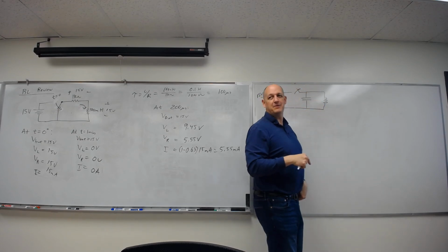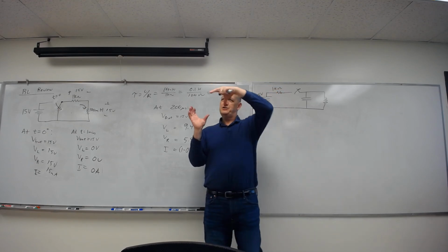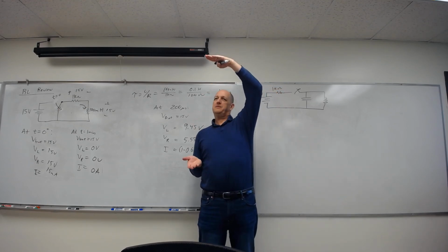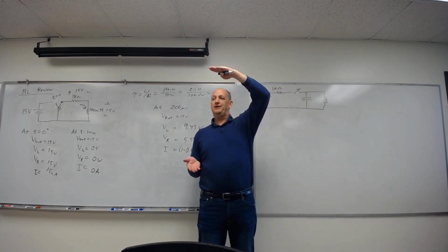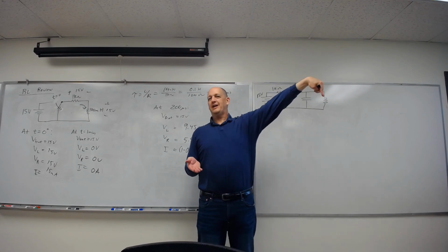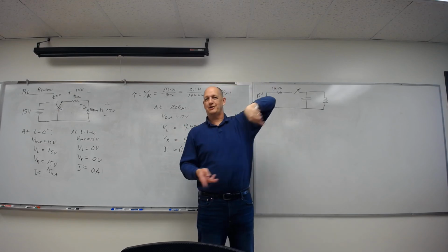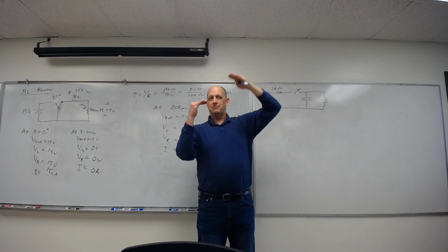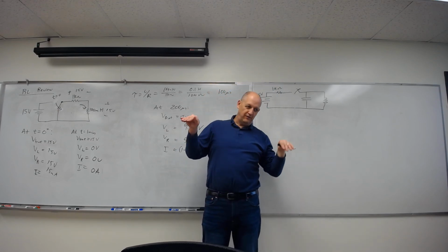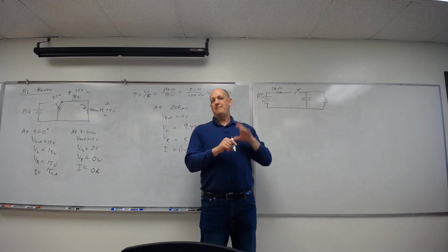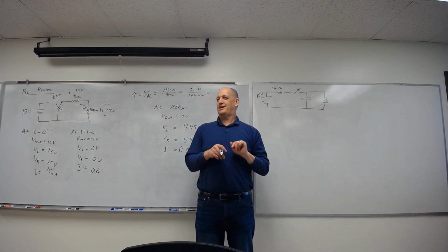to 0 over time, because the energy will build fully on the capacitor and then stop, fully charged. But the inductor says, nope, I'm not going to let current stop. So the capacitor just changes direction to keep pushing current. Then we'll completely drain the capacitor so we have 0 voltage across it and a maximum current, which can't stop.